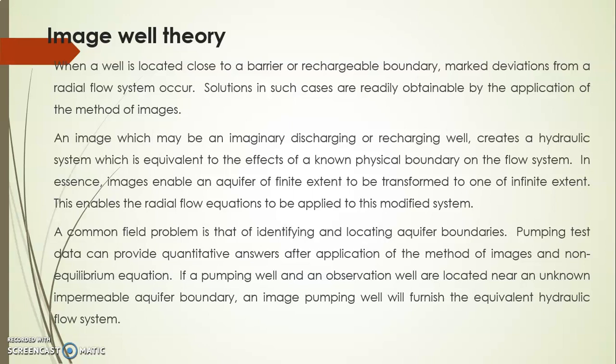In essence, images enable an aquifer of finite extent to be transformed to one of infinite extent. This enables the radial flow equation to be applied to this modified system.